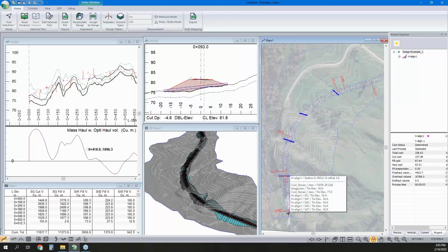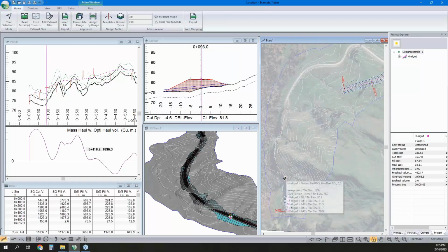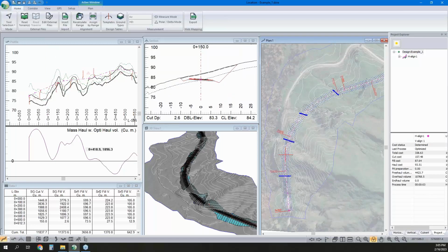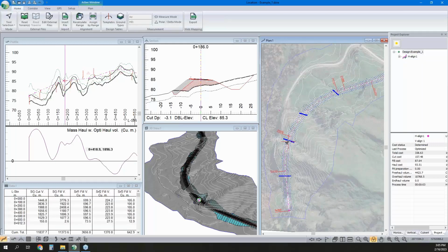kilometer such and such, you're going to have to climb up hard to get on top of a ridge. So you're going to have like a 5 meter deep fill at the start. You're going to go through the ridge with a 3 meter-ish cut, and then you're going to fill that draw in with a stacked rock fill. Without any of these visuals, of course, it's hard to imagine, but just knowing that and being able to communicate that is better than nothing. Now, of course, it's always nice when you take some of these different functionalities and strategies that we're going to talk about and combine them.